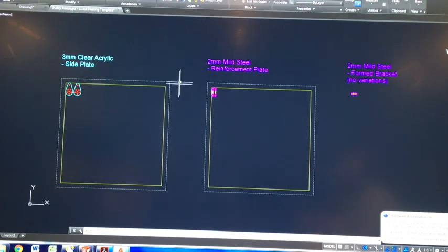So just to explain, the way you would want to set up your file, if you were doing your own project in future, is you would want first to have your material on hand. So you know how big your material is, what the thickness is, what the details are, etc. Then you can draw the size of your material. In this case, this grey outline is the size of the material. The yellow outline is then a nesting size. I've come in maybe 20 millimeters from the edge, on each edge, so I know this is the actual material I can use.